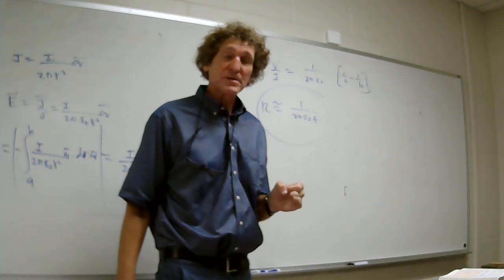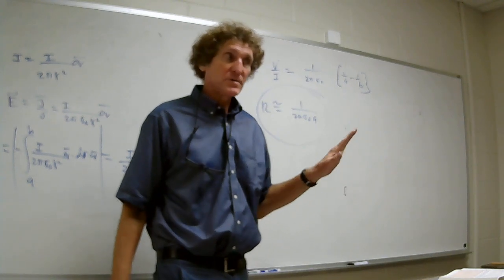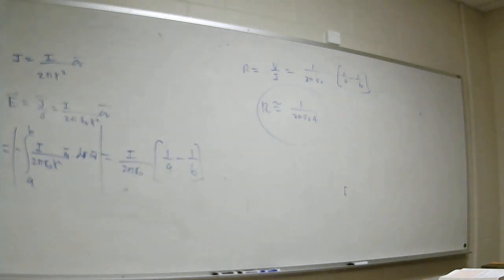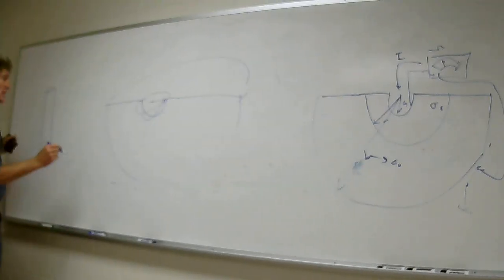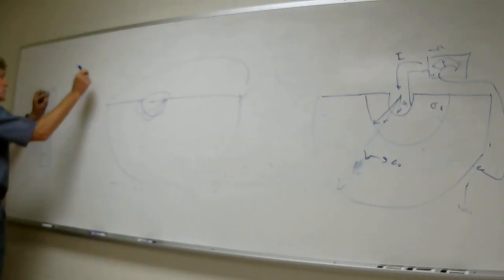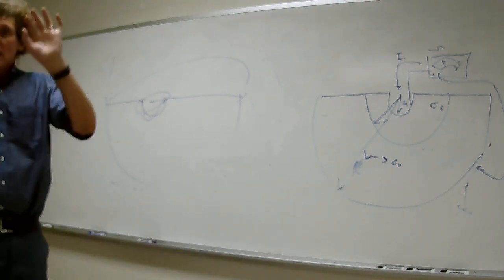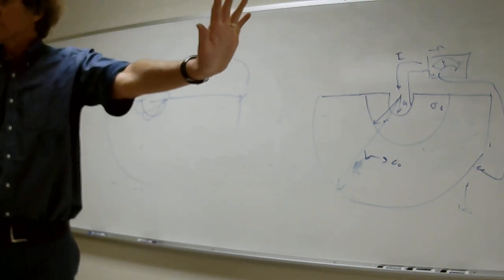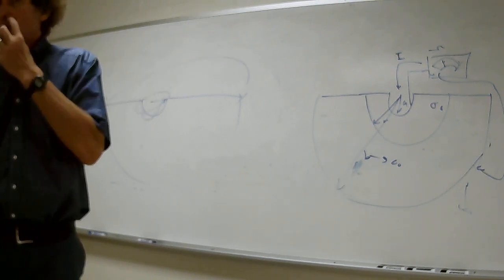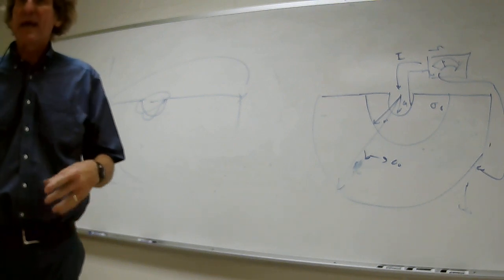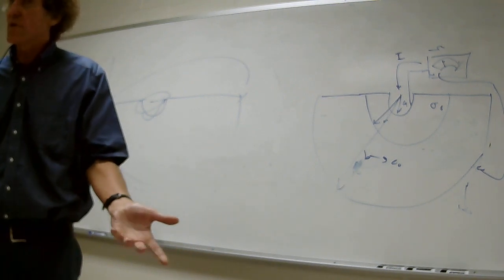Do you all see that? That's an assumption, though, that the conductivity is going to be homogeneous. Usually what they do for calculating things like that is they'll take a rod and drive it down, a deep rod, and then they'll put a grounding rod out there. So now it looks like a cylinder with an infinite actual ground. Follow me on this, class? Now, I'm not going to do that problem right now, but I'm just giving you an application of this. You can use this to estimate the actual conductivity of the soil.